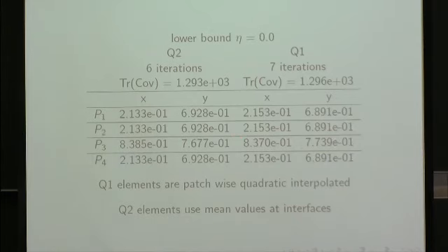Here there are some issues about the convergence of the Newton algorithm, considering the discretization problem and so on. I'm using finite elements, so I can discretize the state using quadratic function, linear function, and so on. You see that using quadratic function, the Newton or this active set strategy converges a bit faster than Q1 for a state equal to 0.